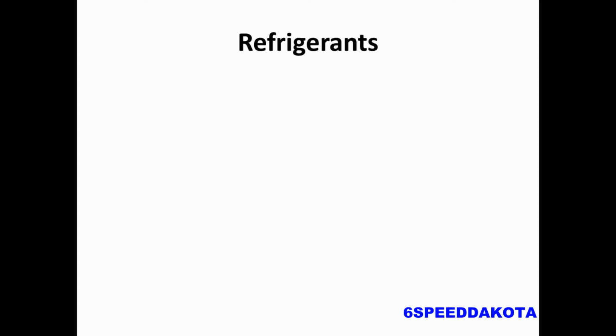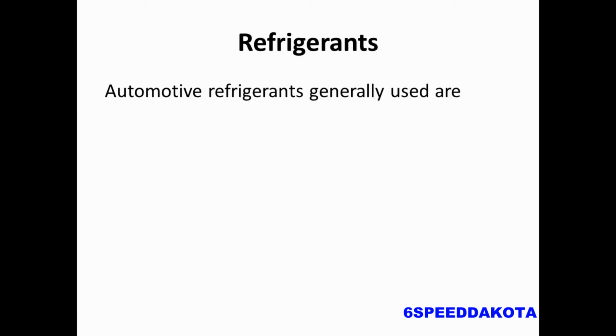So if the compressor is the heart of the system, the blood of the system is the refrigerant. We have a few different automotive refrigerants that are used. What we call CFC R12, also known by its trade name of Freon by the DuPont company. Freon is generally a term that's thrown around, but that is actually only a trade name from DuPont. We have HFC R134A, which is extremely common. It's still used today.